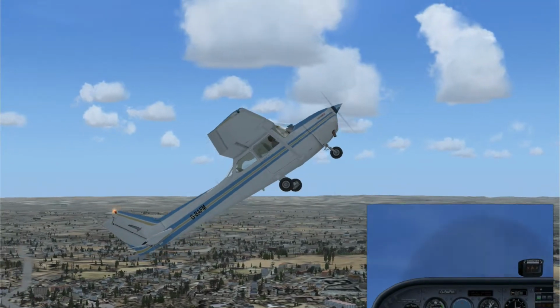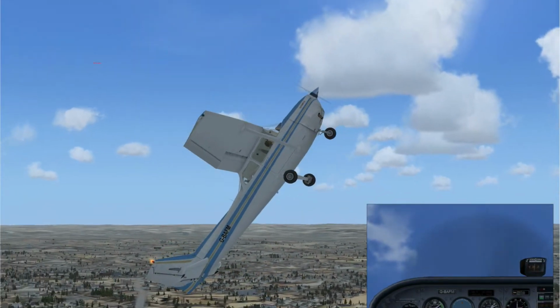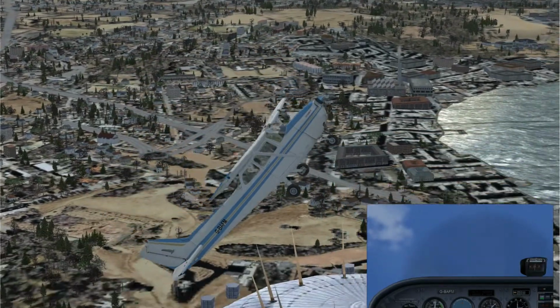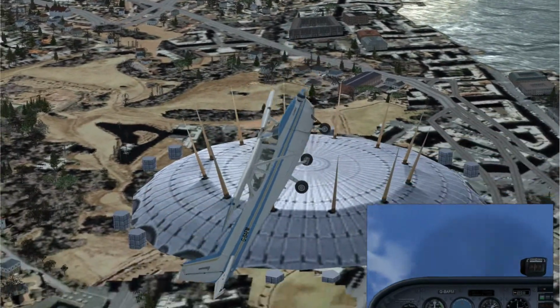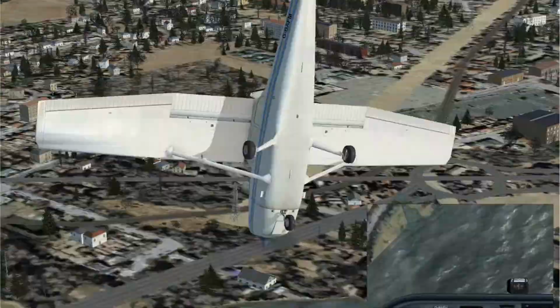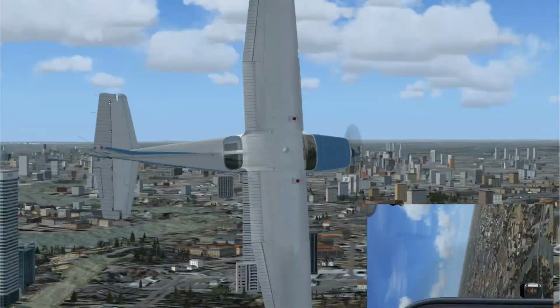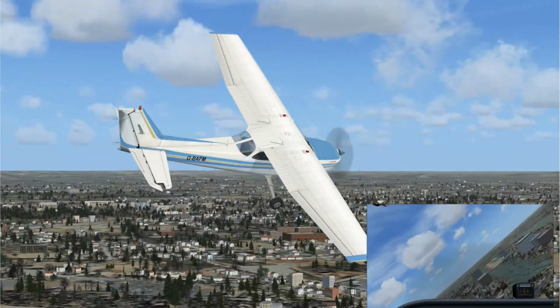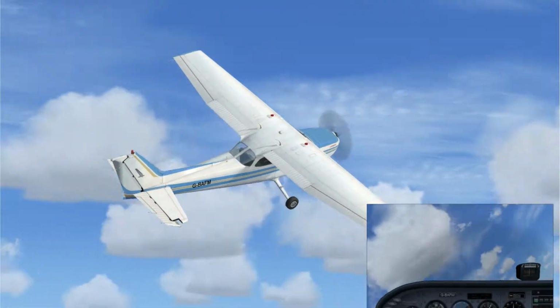However, if the angle of attack goes beyond the critical angle for the aircraft, typically 15 degrees, the smooth air flowing over the surface of the wing breaks away, becoming turbulent, and all lift is lost, causing the aircraft to stall and potentially fall out of the sky. The pilot can control the angle of attack by pitching the aircraft upwards and downwards.